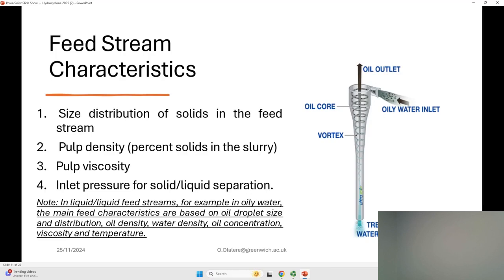Let me give an example. In the distillation process, the design of your distillation column, number of trays, and the rest will be dependent on the type of liquid or the characteristics of your crude oil. And that is a problem we have in different countries. Most times, if you don't change the configuration of your distillation column and you bring crude oil from another country, the purity will be impacted.